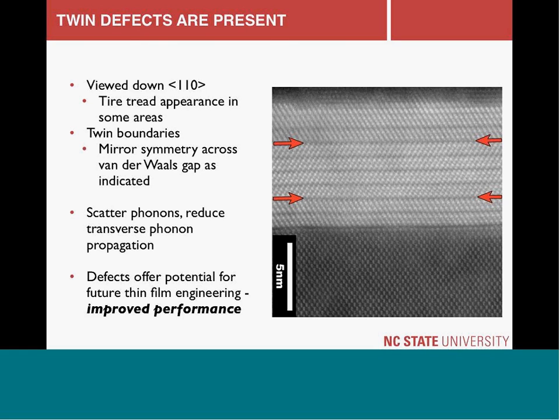Again, defects are going to modify the phonon density of states and cause changes in either thermal conductivity or electrical conductivity. And again, by modifying and controlling this, we're able to modify and engineer these materials at scale to give the properties they desire for thermoelectric devices, whether it's for cooling or heat scavenging for energy efficiency.